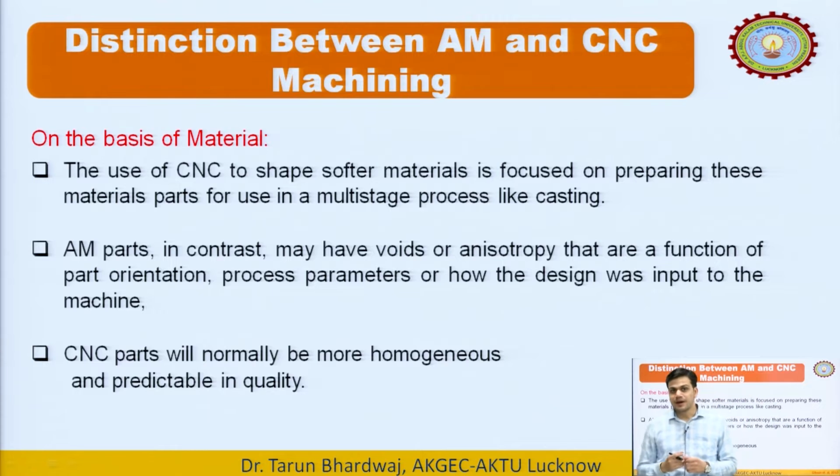But in AM parts, there may be very wide anisotropy. That is basically because of the development of your product, and that is due to the process parameters that additive manufacturing has, because this anisotropy is basically due to the thermal gradient that is there when you are creating the object.